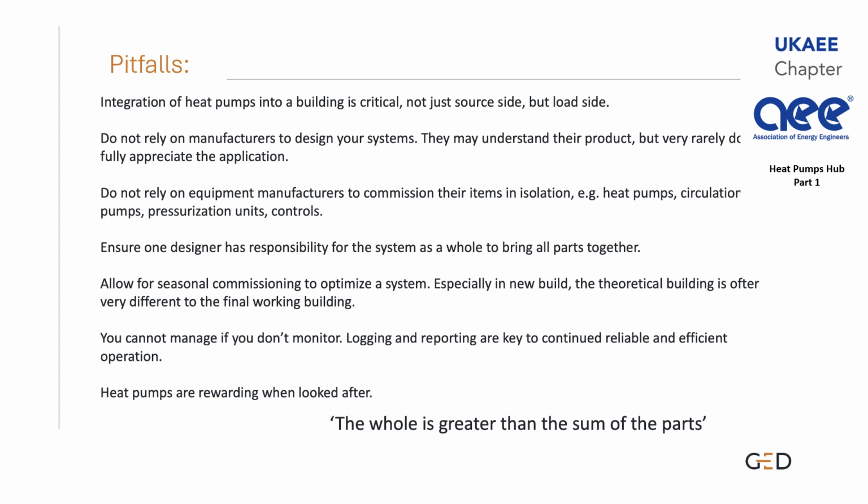Allow for seasonal commissioning to optimize the system, especially in new build. The theoretical building is often very different to the final working building, and you cannot manage if you don't monitor. Logging and reporting are key to a continued reliable and efficient operation of the heat pump systems. Heat pumps are rewarding when they're looked after. And to quote Aristotle, the whole is greater than the sum of the parts.